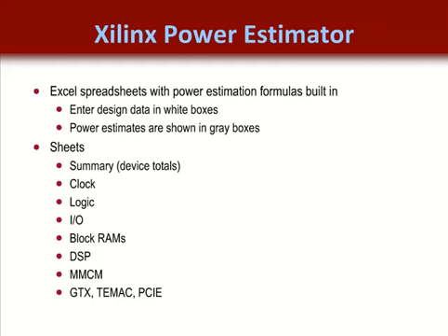Unlike data paths that may contain multiple LUTs and nets in series, data paths that use the dedicated hardware resources do not require any programmable routing delays, except to route to and from those dedicated resources. Another reason to use the dedicated resources is that compared to soft implementation, that is a LUT and register implementation, the speed is significantly higher. So be sure to use as much of the dedicated hardware resources as your design needs, and if you think you may be running out of the primary FPGA resources, consider implementing more of your design in leftover dedicated hardware resources, like the DSP slice or block RAM.